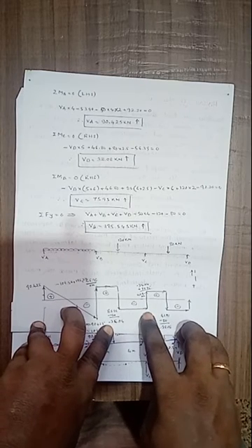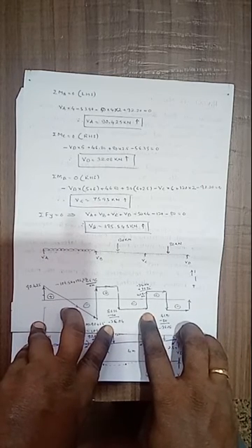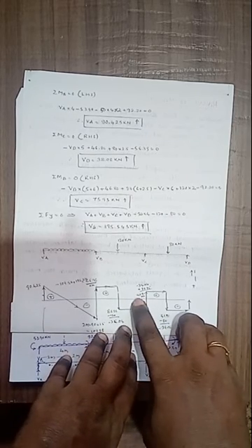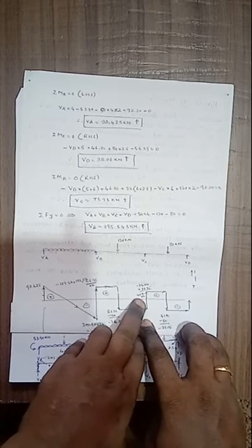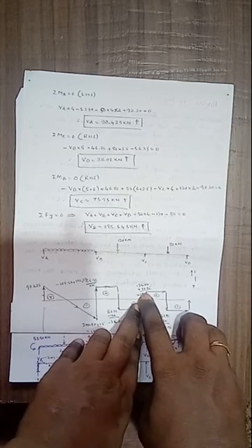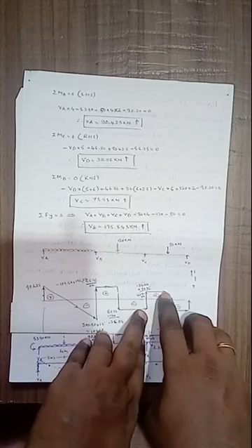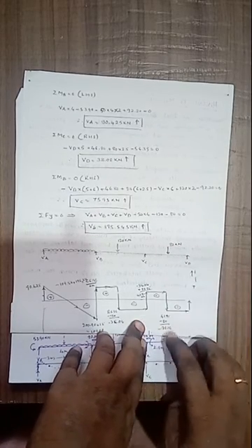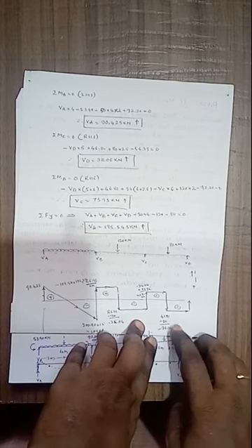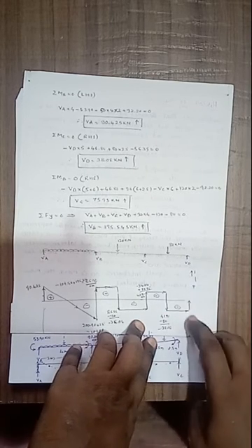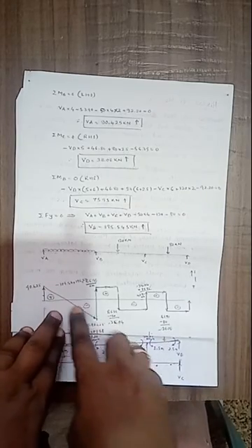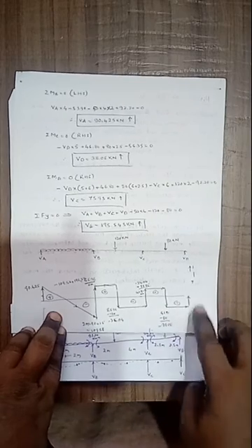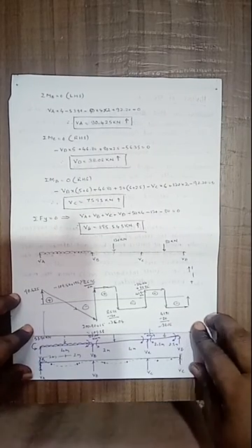Then that remains constant up to C, that is negative. Then here there is a support reaction VC, that is minus 34.04 plus 75.95, that becomes 41.91, that one is positive. Then it remains constant. Here I have shown the arrow mark. Then because of this point load, that is 41.91 minus 80, that is minus 38.08. Again there is a support reaction, that becomes 0. Here the variation of the shear force I have shown by the arrow mark like this. This one is regarding the shear force.